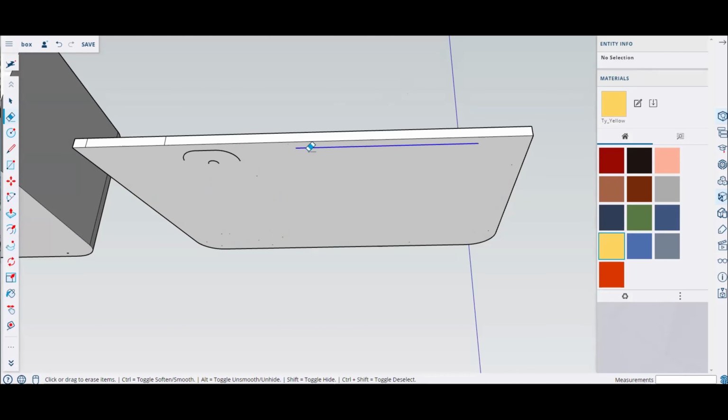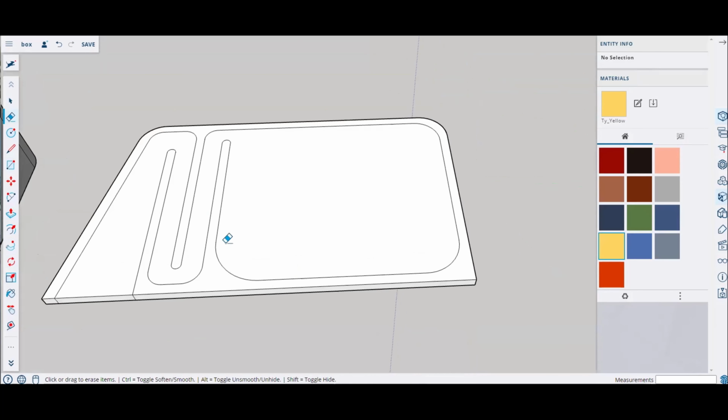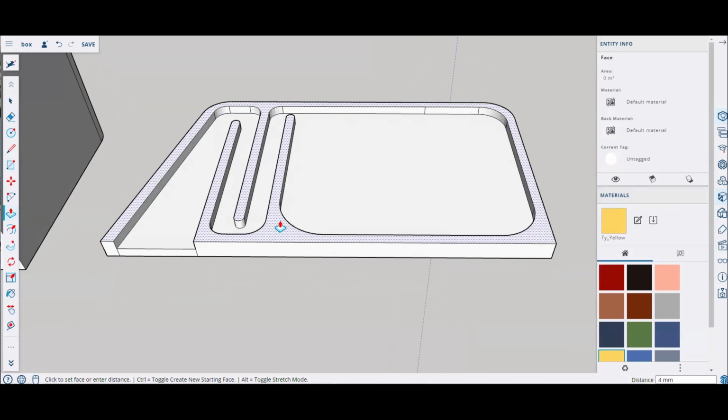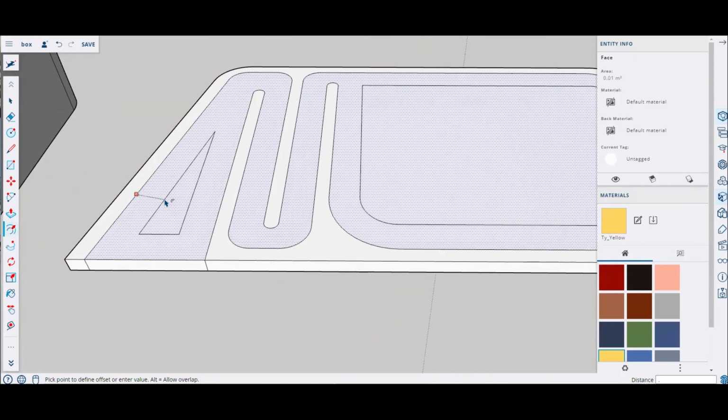And what's quite simple in terms of the process here, because I've still been working in 2D really, and now I'm going to the 3D part. Okay, and then I'm going to bring this, I have to do that little offset that we said of 0.5. And then we can bring this out to extrude. Just press the button, 2 mil, and bring this out flush.